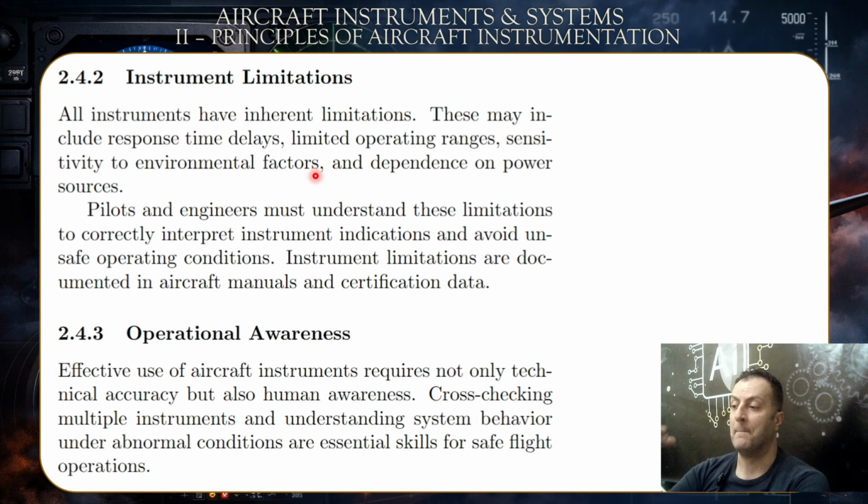Why? Because the aircraft is actually depending on these values to display the current airspeed, altitude, and VSI. So changes in air pressure would change these values and display something that wouldn't be accurate at the moment. Even if it's momentary, it won't be an accurate value. It can be a little bit confusing at times.